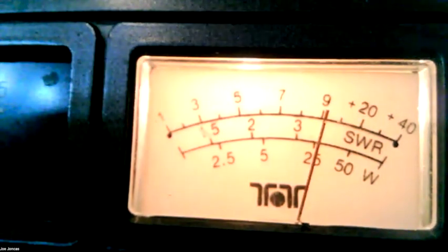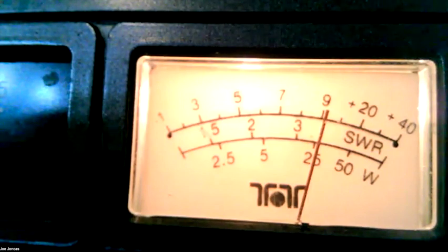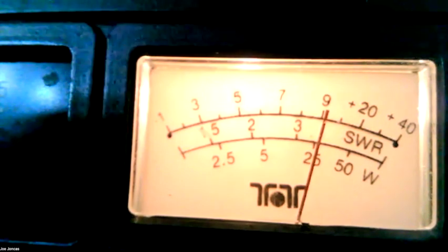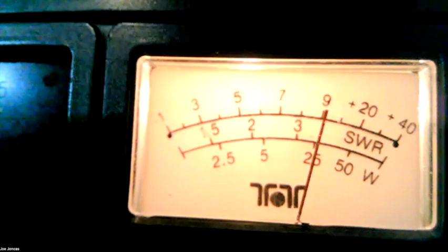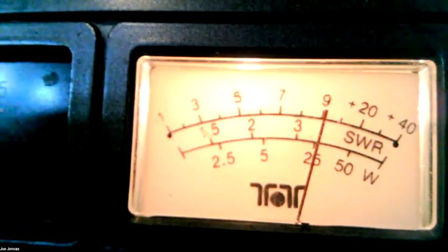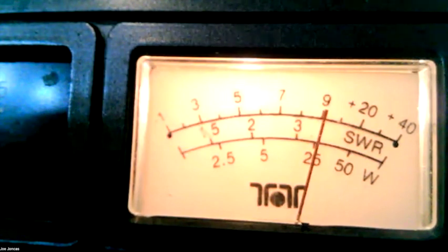Okay, here we see S9, and I'm just slightly over, I see. Now that's 50 microvolts. Follow that? And this is what you're going to have on your radio. Somebody's transmitting to you, and if they're hitting you at S9, that's a strong signal. And that's above most noise, although sometimes in the city on 80 meters, you get an S9 noise level, which is almost impossible to deal with.